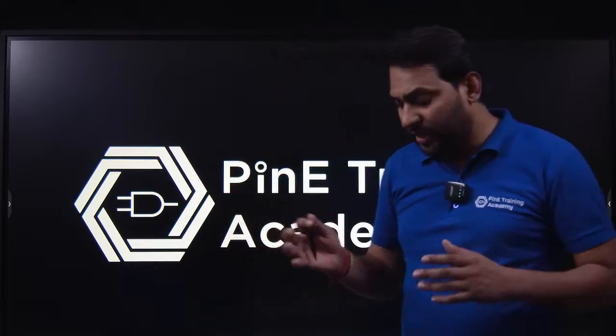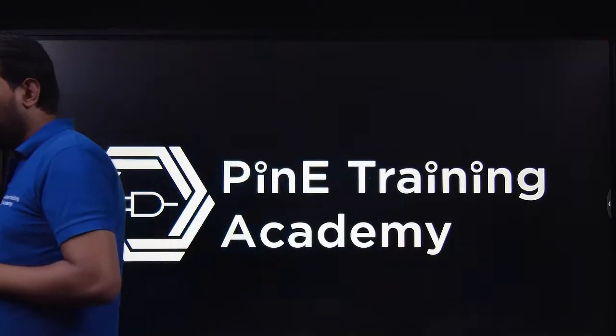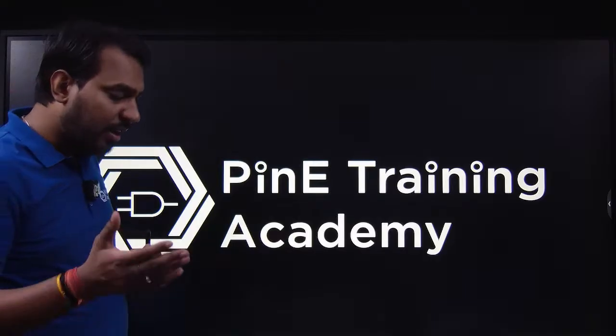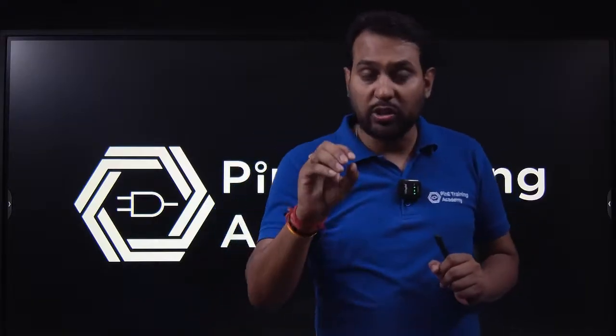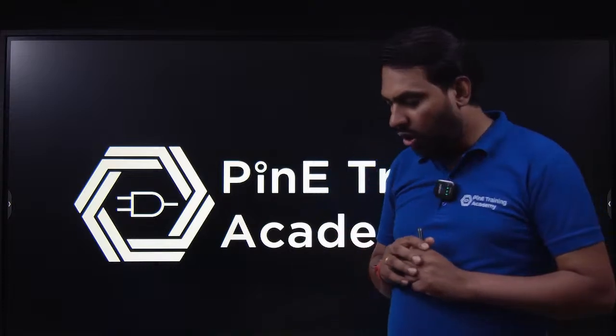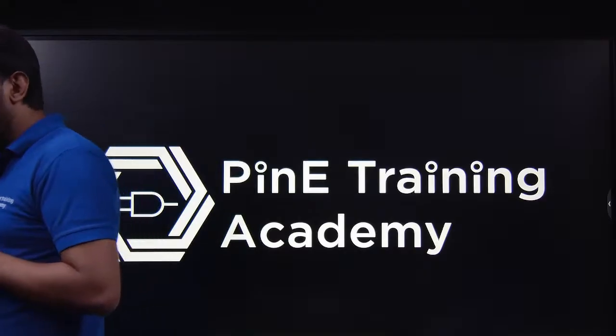We have a lot of layers, and metal 1, metal 0 to metal 7 or metal 9 as per the specification. In the layout you must focus on arranging your transistors in such a way that they take minimum space, and the routing should be very good so that it has minimum IR drop.